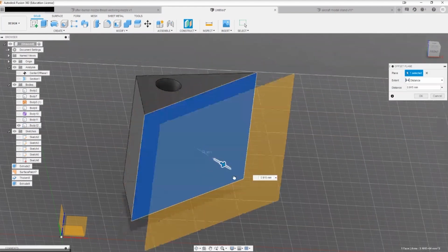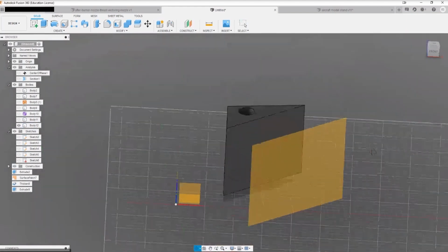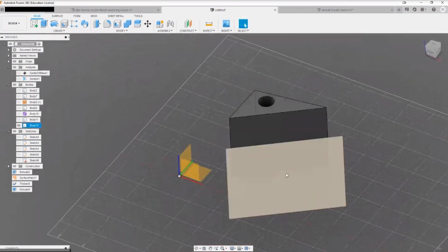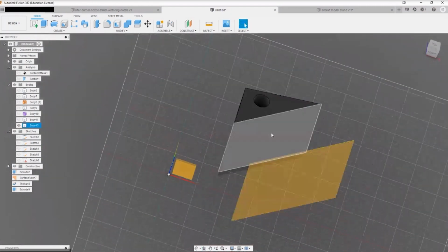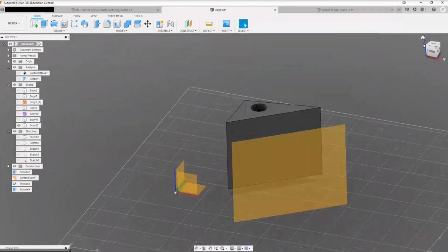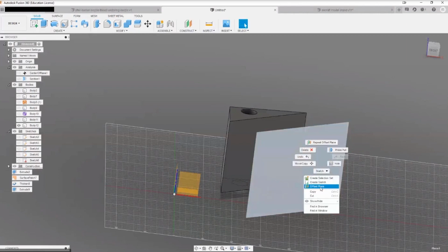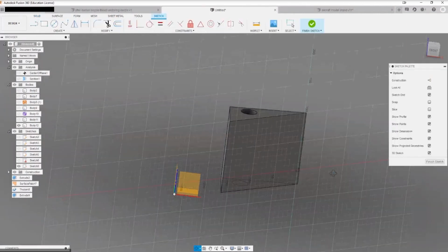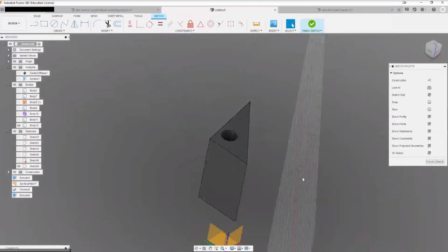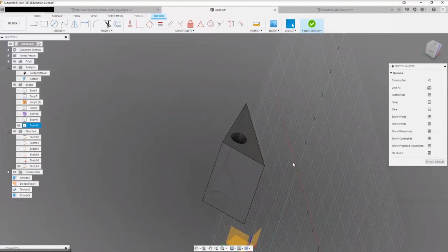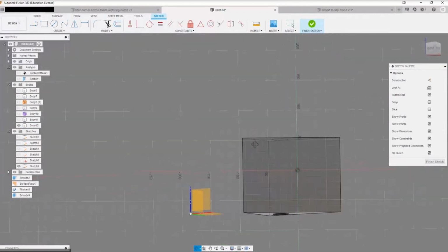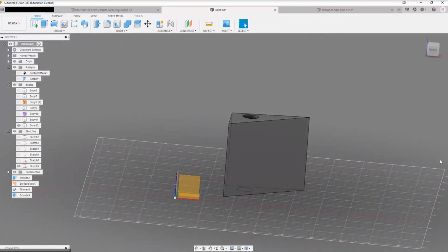So you can create a construction plane that's out here. Now, the advantage of this one is that you can create an offset sketch for this face, but it's not one of the XZ, XY, or ZY planes. And you can right-click on that and go ahead and create a sketch over here. So you can see the plane of it is offset. All right, so that's another tool that you can use. I highly recommend looking into that. Right.